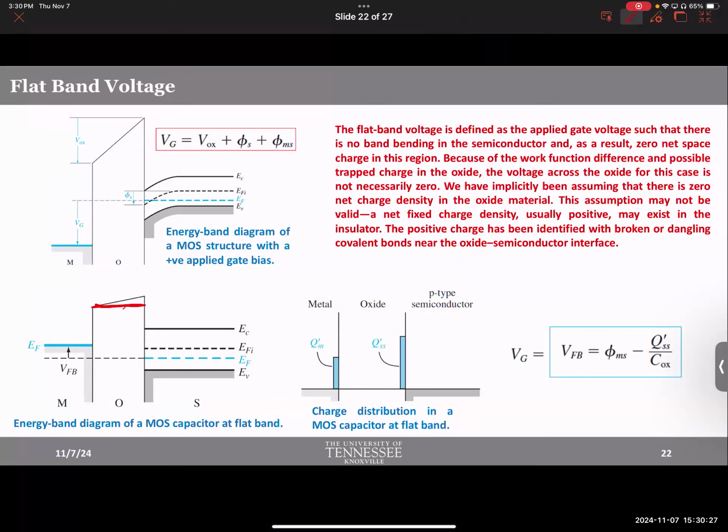The exam question, or interview question, could be: okay, if I give you a flat band diagram, maybe you are lucky, you have a perfect oxide. Then what will happen here? This is not going to be there. No charge in the oxide because it's flat. Perfect oxide, right? But because of broken bonds and imperfection, there are some internal trap charges, fixed charges in oxides.